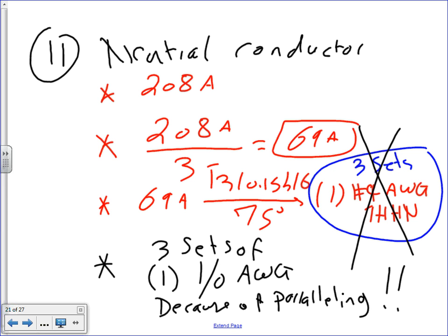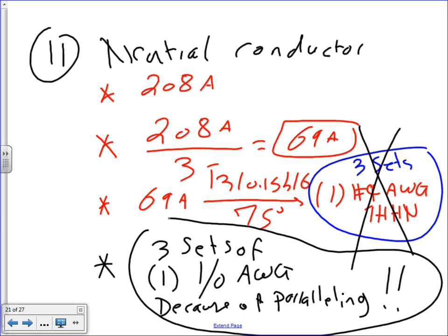Let's go to the fuse. So this would be my answer, because if we were not paralleling, then it would be number 4. Now, would it be wrong if I multiply by 1.25? No, but knowing that's a neutral load, guys, we already went higher anyway.